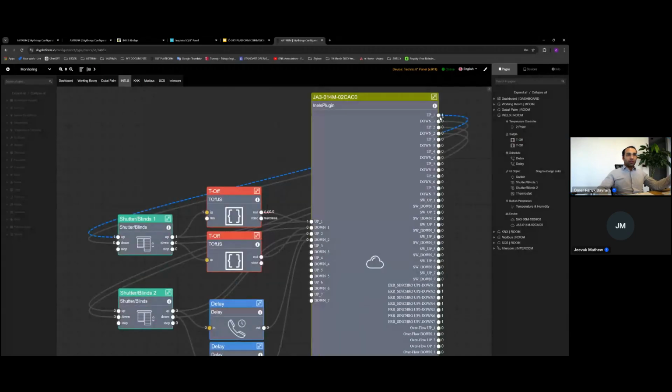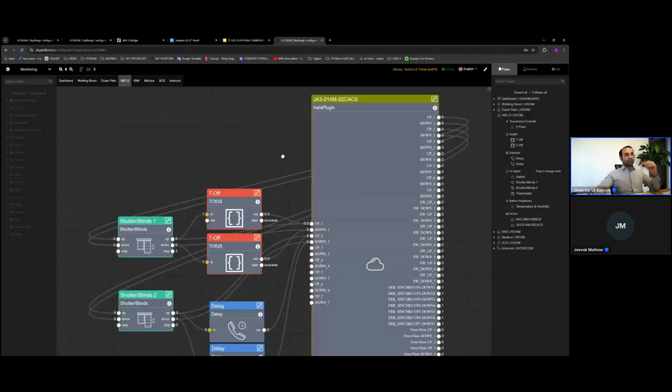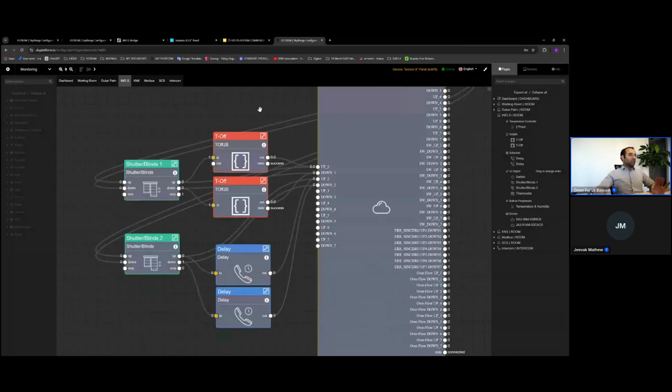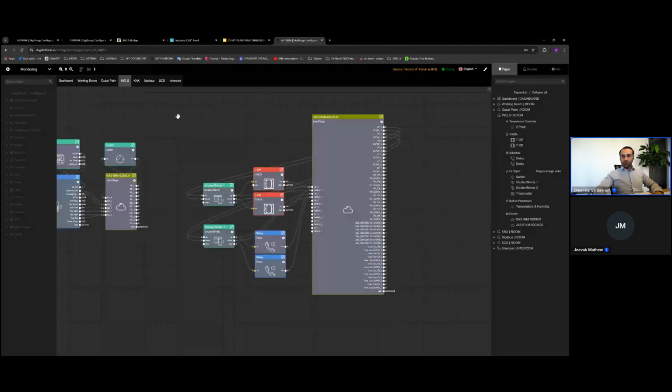Yes, closed, because I have set 5 seconds uptime here. Let's close. Yes, as you can see, the close relay feedback comes here, and after 5 seconds, it's closed. Let's stop, open, and stop. So no need to wait every time to reach the upper and lower limit. Okay, this is the shutter blind side. I'm gonna speed up a little.